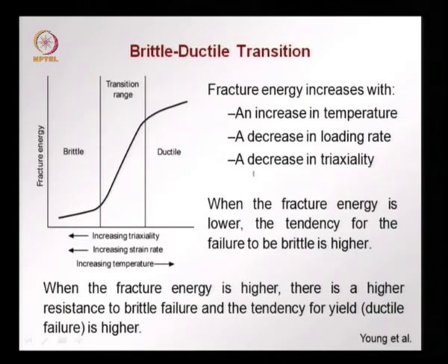A third case which shows an increase in fracture energy is a decrease in triaxiality. Triaxiality is the confinement and the degree of constraint. As you remove constraints, the fracture energy increases, as opposed to when you have increasing triaxiality, the fracture energy decreases and you have brittle failure.